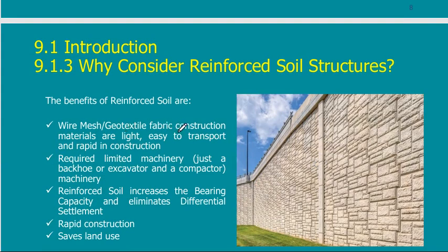By the way, we are going to see photos for them later. These materials are light, easy to transport, and rapid in construction. You don't need to carry lots of materials. If you want to construct a wall, you need to carry bags of cement, reinforcing bars, and wooden pieces for the forms. You need to carry lots of material. But here you don't need anything except the facing and a few strips or a few meshes.